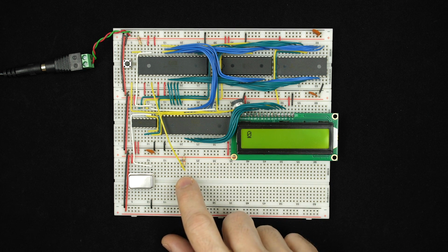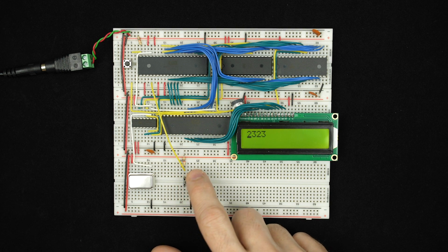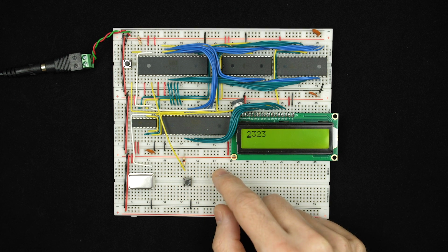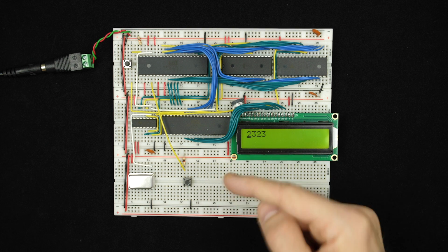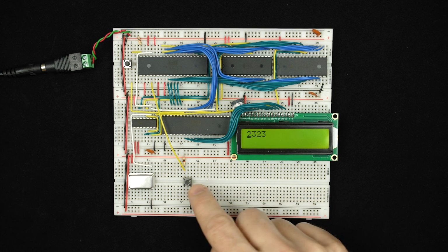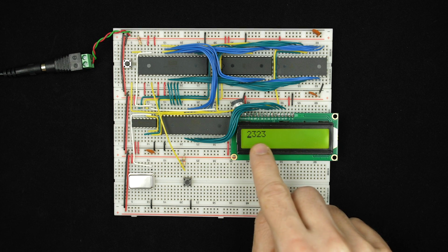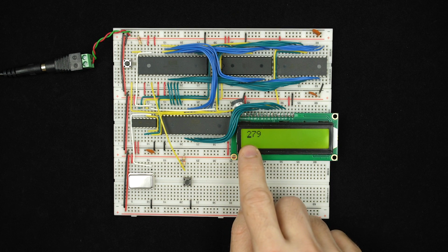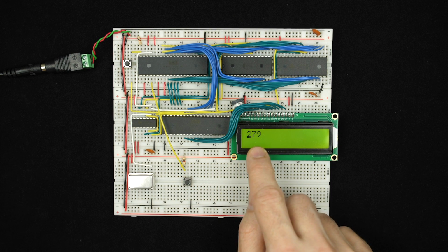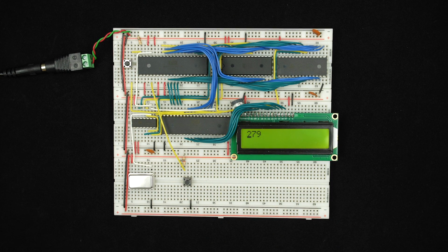The problem is that when I press the button, the interrupt handler runs and increments the counter so quickly that as soon as it increments it, I'm still pressing the button. So it goes right back into the interrupt handler and increments it again. That's why when I press the button, the counter is incremented a bunch of times. It's so fast that no matter how quickly I press the button, even if it's pressed for just the shortest split second, the interrupt handler will still run hundreds of times.